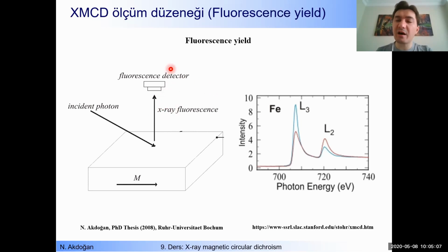In order to produce a current, which is proportional to the number of photons coming to the detector. So since we have current within the detector, it can also be affected by the external magnetic field you applied during that type of measurement, okay? So it is better to use the magnetic field, if required, before the experiment, and during the experiment, don't use a magnetic field. It is not advised.